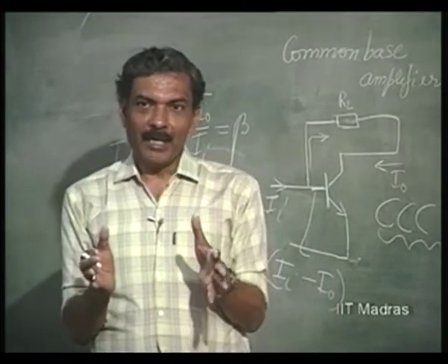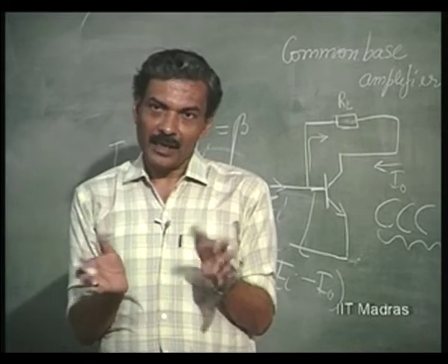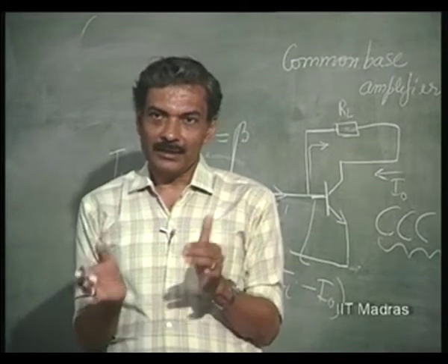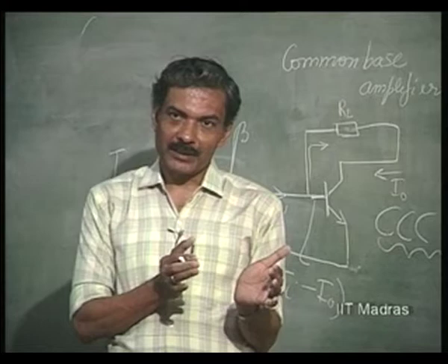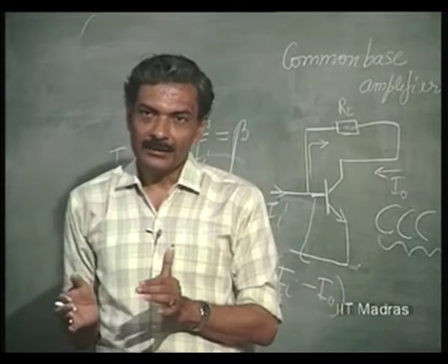The fundamental amplifier which we had considered earlier is the common emitter amplifier, and negative feedback configurations are common collector and common base respectively, with total voltage and total current negative feedback.